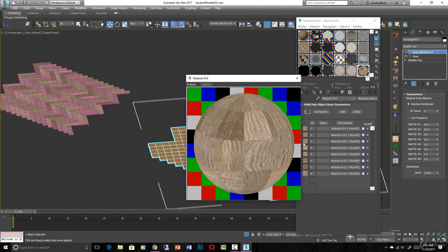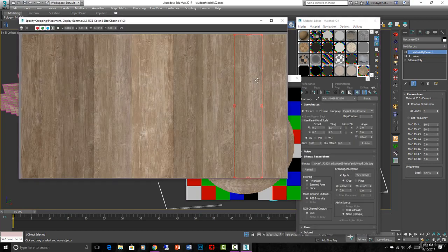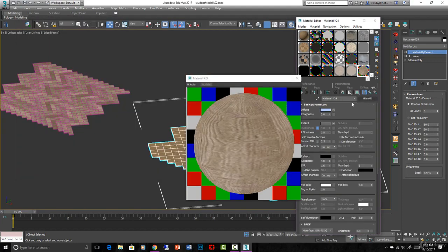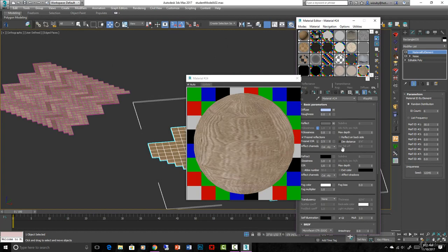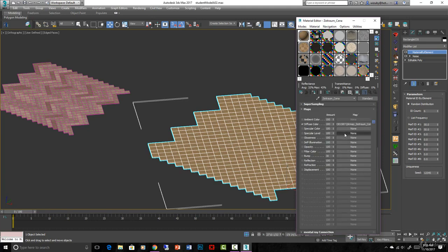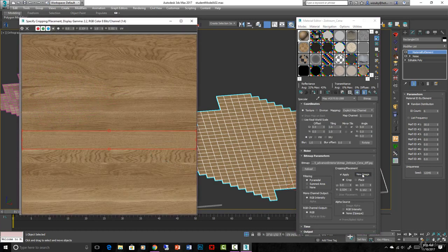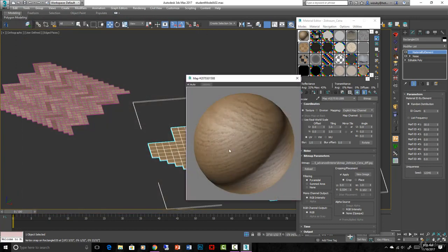They look terrible in here because my rendering's set to standard right now. And these are Vray materials. But there's the image. Okay, so all I did was basically take this image. Well, I set up one material, right, with that image. And if you look in the reflection, it's cropped in the exact same place, but it's a reflection map now. Well, let's do it so we can see. Okay, so take this, copy, paste it into your specular. Again, it's got the same crop. You would change this now to a reflection map instead of the diffuse map, but we'll use it just as is right here. There you go.